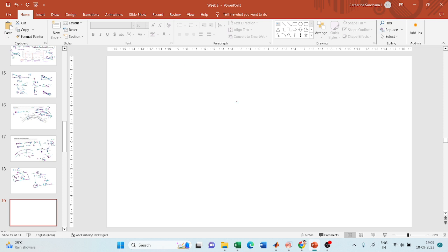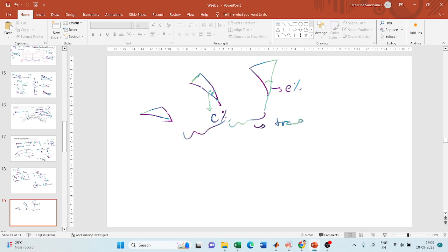At this point, it is going to have a camber, a triangular section like this with a slope of camber, and at the start of the horizontal curve, it is going to have a triangular portion like this with the slope of super elevation. So this is where you will call it the transition curve. Here it is called the tangent runout, and some portion of super elevation runout.